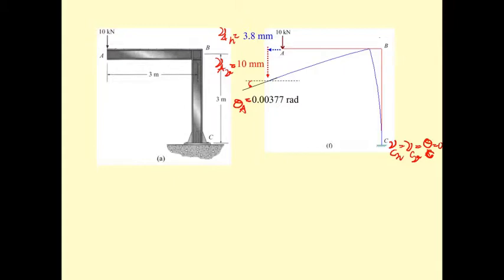And since the beam has no axial deformation, the same as the column, what we have is this: V sub BH is going to be 3.8 millimeter. And over here also, V sub BV is going to be 0. This is a rigid joint, this is perpendicular. If you reference it with this, this is going to be theta sub B. You can determine it by putting the 1 unit moment at B, and then you will get the result of this.